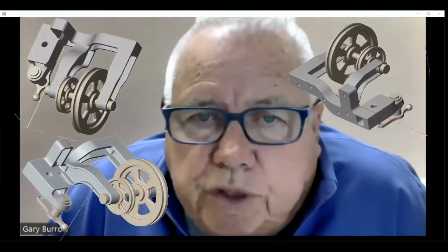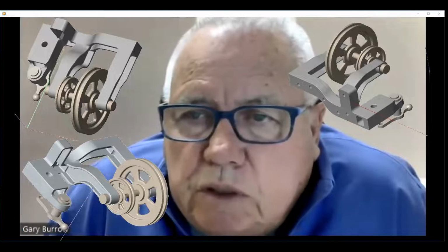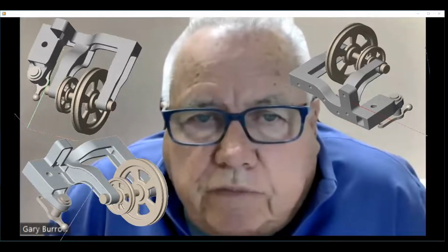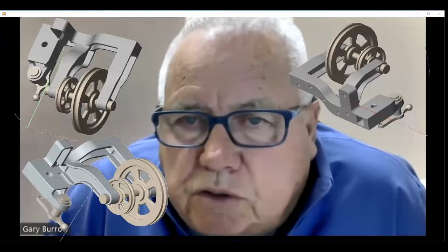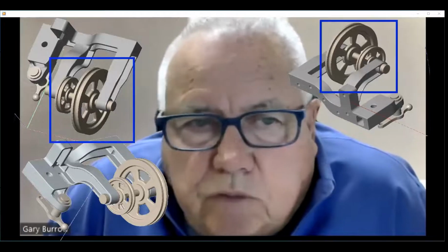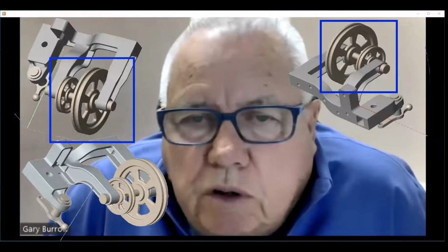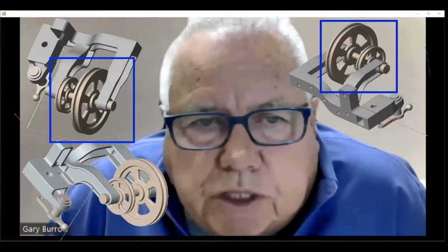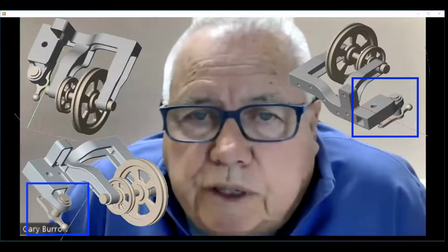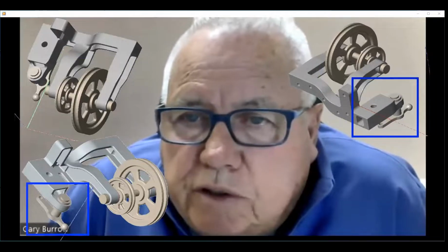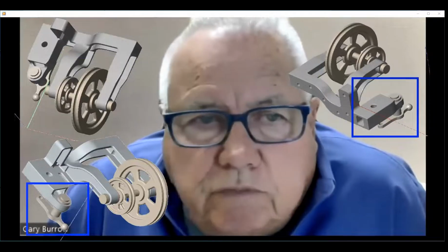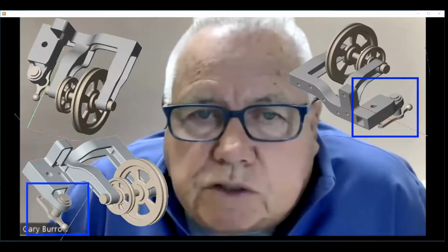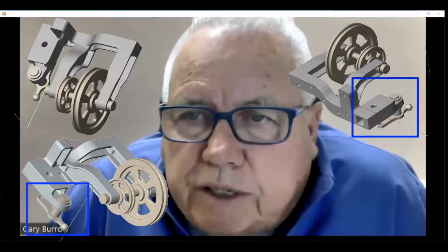Here is a relatively thin-walled, lightweight aluminum casting designed typically for military aircraft from the 1950s, 60s, and early 70s. With mechanical flight controls, the 2 pulleys are a redundant cable system for controlling a fighter jet's rudder. The ball joint and the lever actuates a nearby cockpit canopy vent via a linkage. The vent is intended to be open on the ground at taxiing speeds.